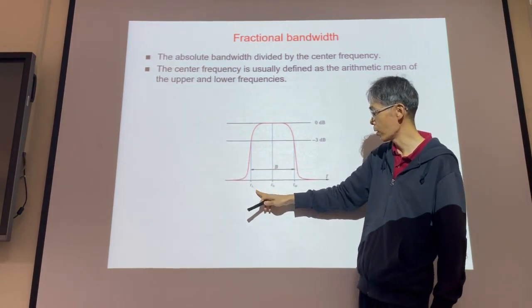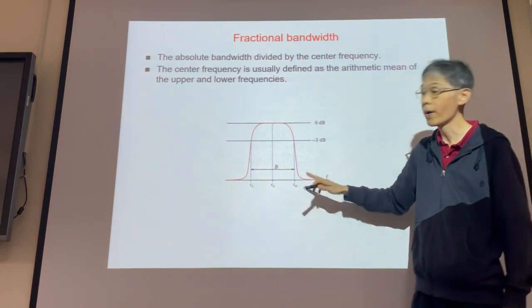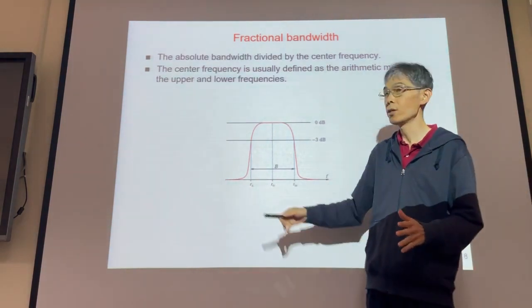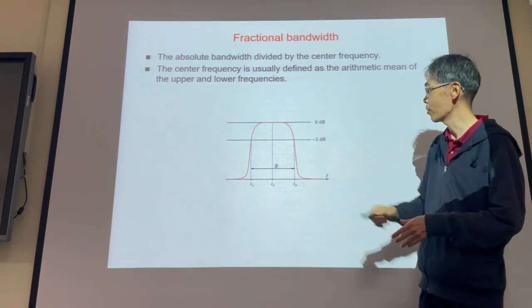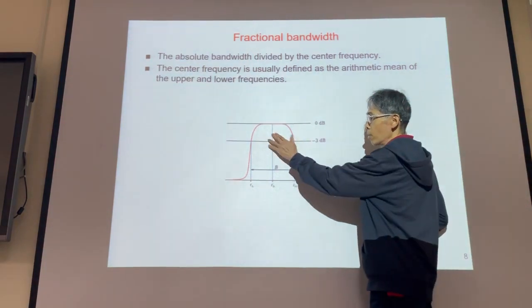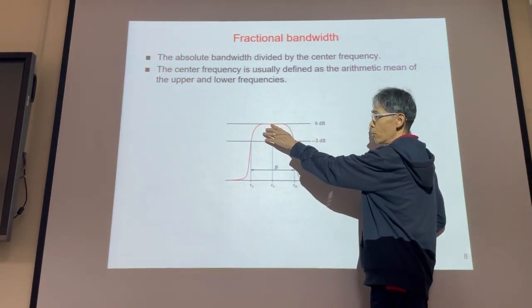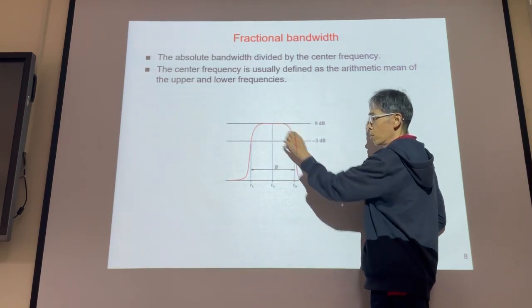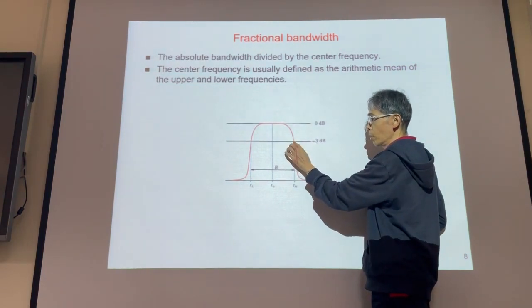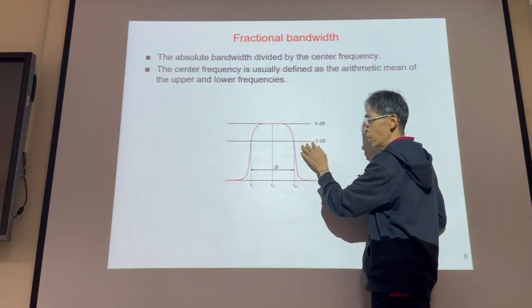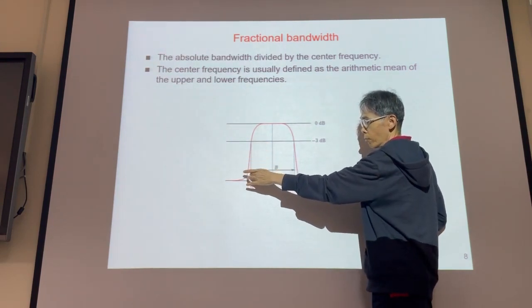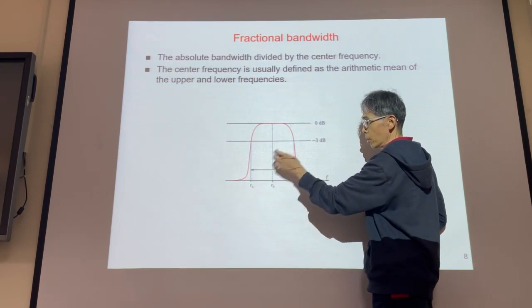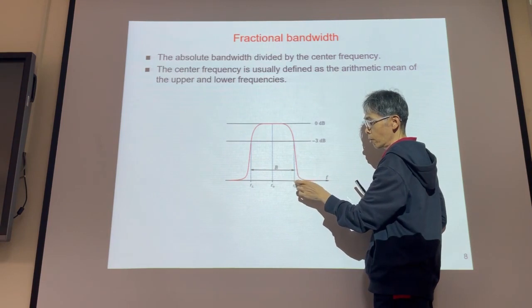So this is the band pass filter, from frequency FL to FH. Between this range, signal can go through. And this is the peak amplitude. If this is the reference, from this magnitude you go down 3 dB, minus 3 dB, and draw a vertical line to the frequency axis at each of the two points.